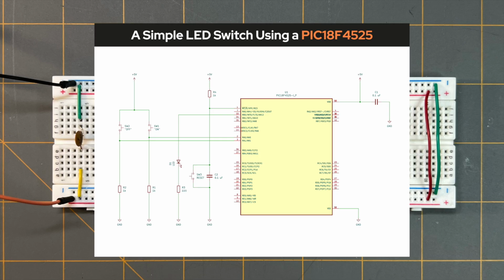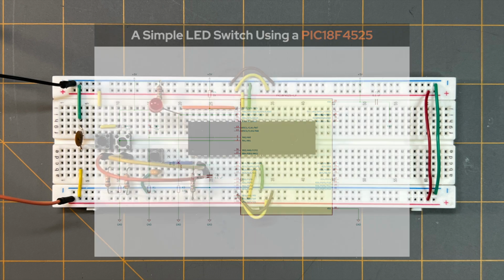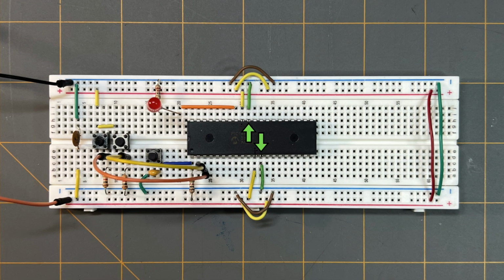This capacitor acts to help stabilize the supply voltage feeding into the microcontroller, which is crucial for its operation. Both VSS pins of the PIC microcontroller will be tied to ground, as can be seen in the schematic for this project. Pins 11 and 32 of the PIC microcontroller are its VDD pins.